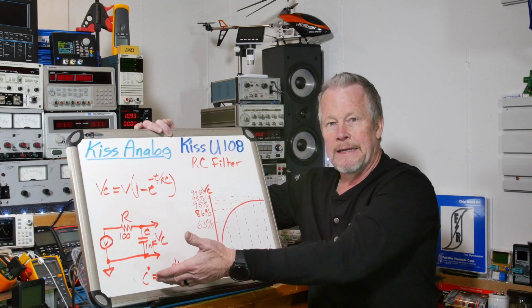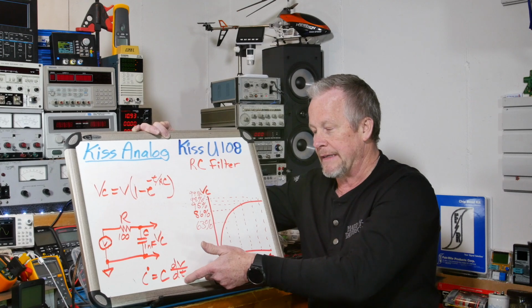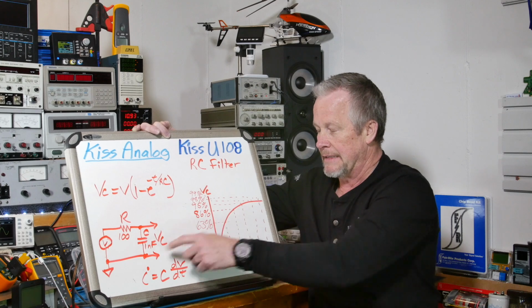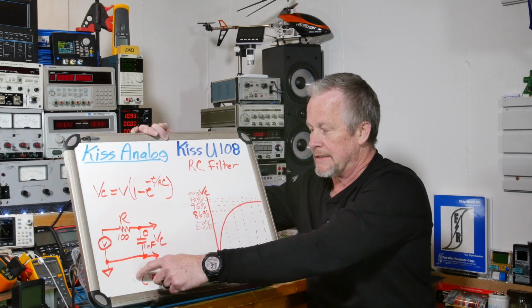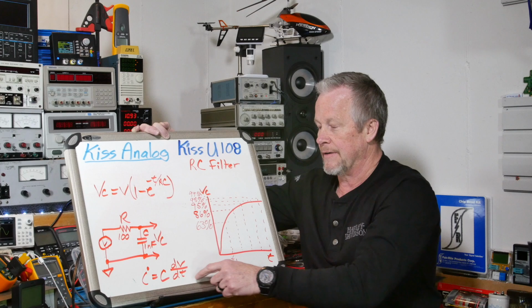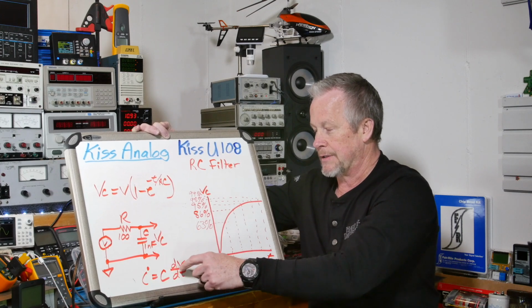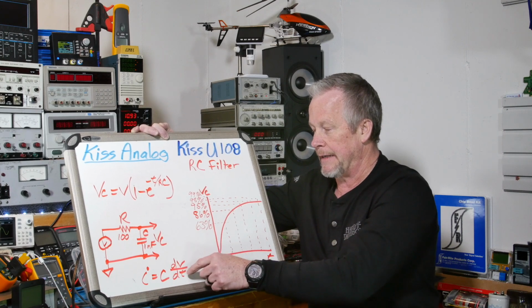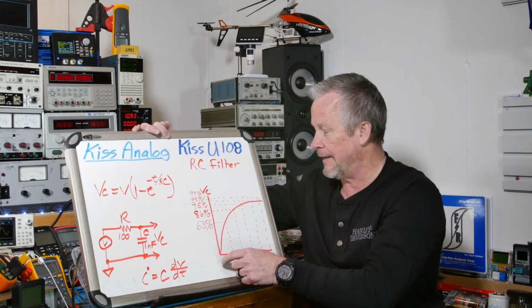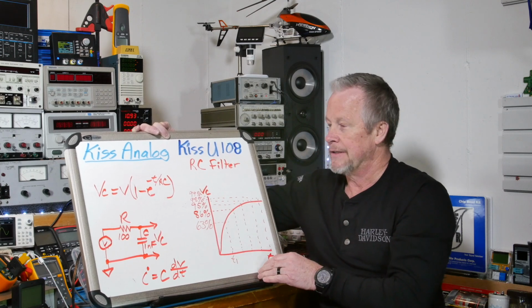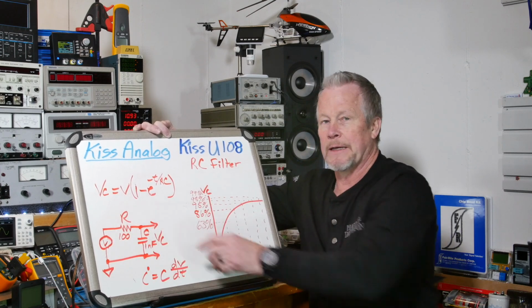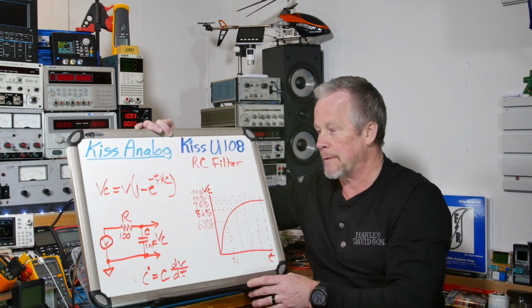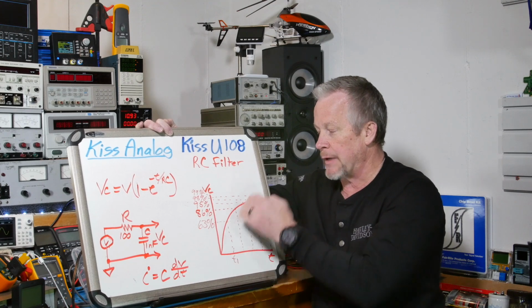And now the thing is, you don't really know what the dt is. If you're going to solve for dt to see how long it takes for that to happen, then you solve this equation. So the dt is over here and I is under here. So dt is equal to C times dV divided by I, and I would be the current charging the capacitor, which would be the voltage divided by the resistor. Okay, so this is an approximation formula. It works for straight lines.